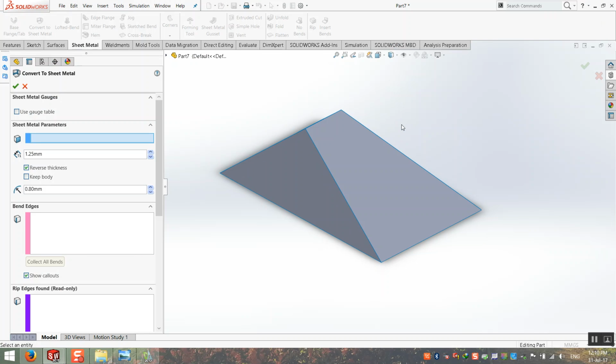And we discovered that this material, 2 millimeters, for example, yesterday, if you forget, it's made by 2 millimeters. After a check, we found that 1 millimeter is also okay. So I can save 50% of material based on this structure. This was a real job study, a real case study. We saved when we made it from 2 millimeters to 1 millimeter. We calculate the quantity. We saved almost 83 kilos.